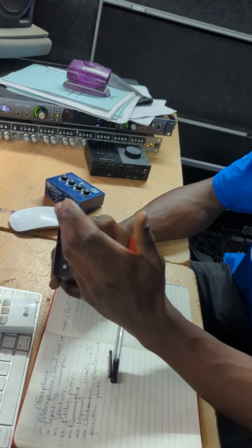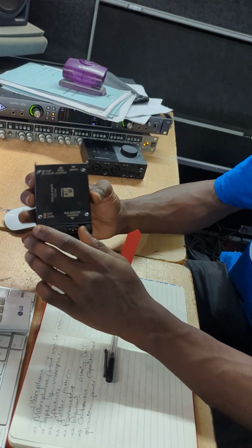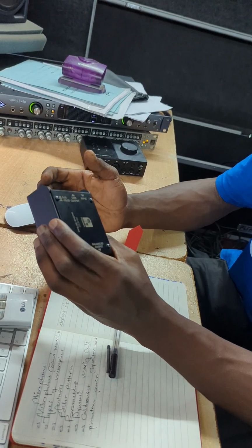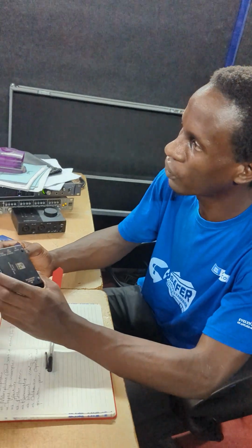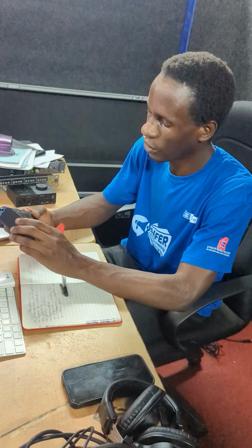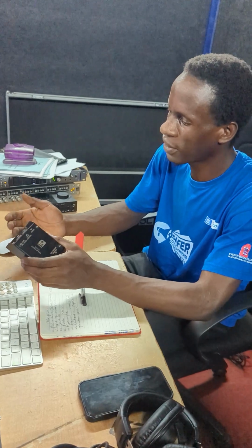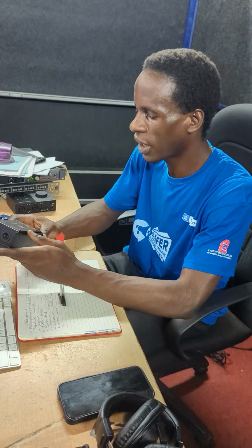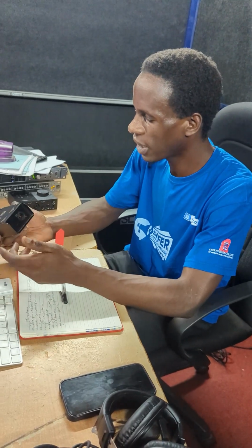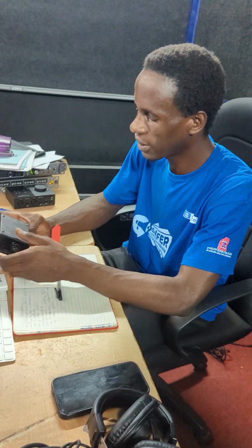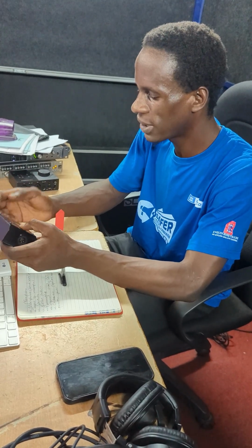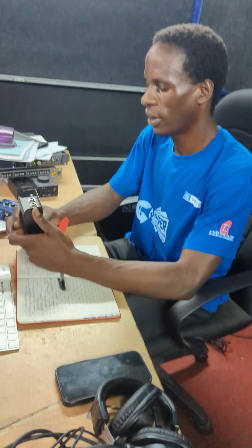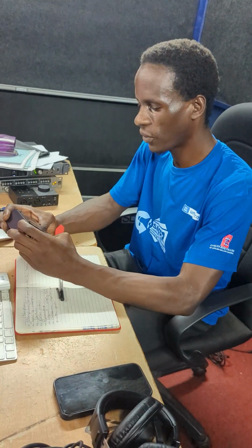So when the signal comes in unbalanced, it will leave this DI box to a level where we can say this is good, and it's not going to have any phase in it. It's not going to lose strength, and this is very important when you are running long cables. So between the instruments and the long cables, you can put this so that it converts that unbalanced signal into a balanced signal. Okay. Having said that, I think we are done.